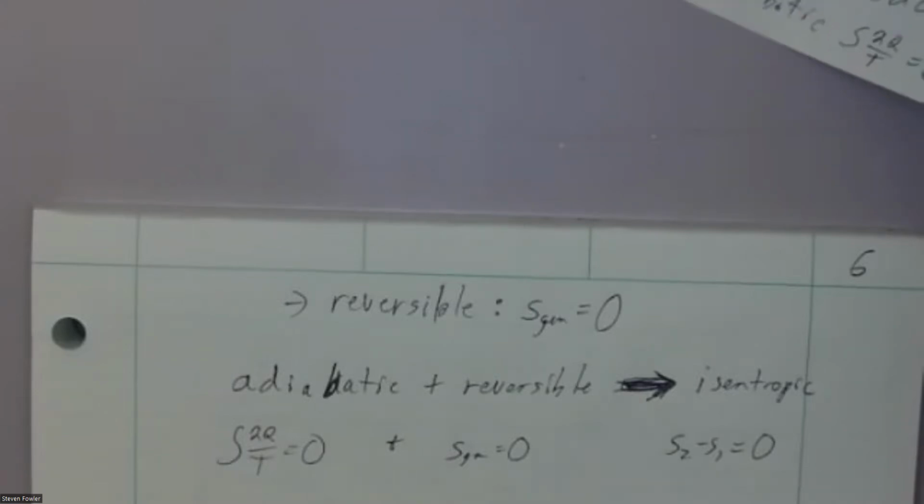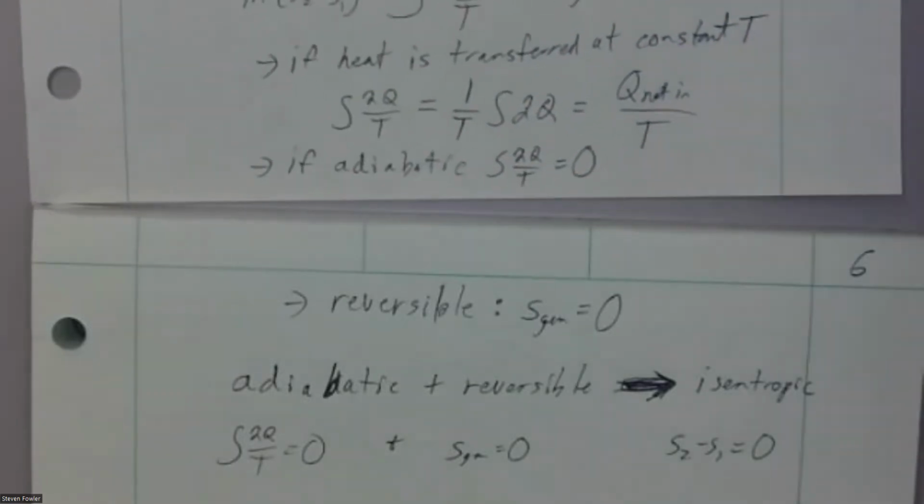Okay? It's a very specific scenario. The best example I can give you is a phone charger once it's operating normally, once it's kind of settled down. It's losing heat, right? That phone charger is losing heat, but if it's hitting a steady state point, some kind of equilibrium, the entropy of the phone charger components is going to be a function of temperature. So if it's losing heat at a constant temperature, then it's basically losing entropy at the same rate it's generating.